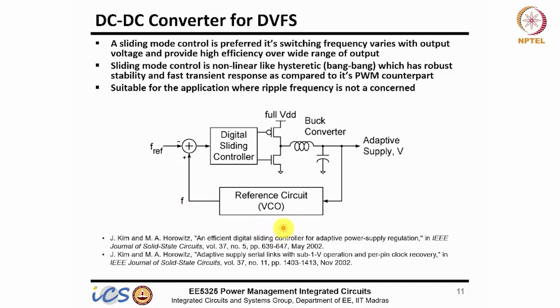The reason we are using a VCO is because your delays are measured in terms of inverters actually. If it's implemented using a ring oscillator, which is nothing but cascaded inverters, then it will represent your digital circuitry, whatever logic gates and everything.